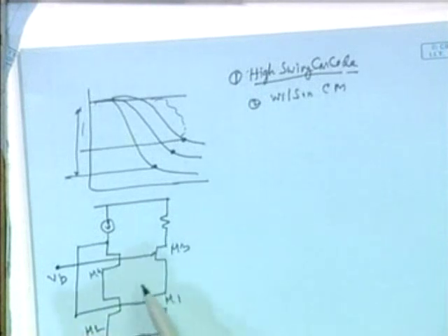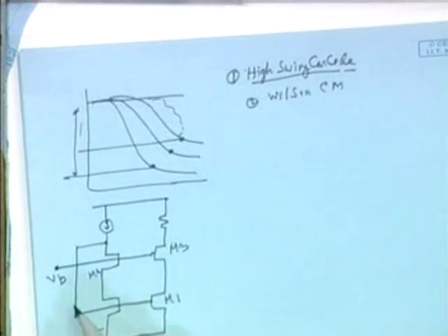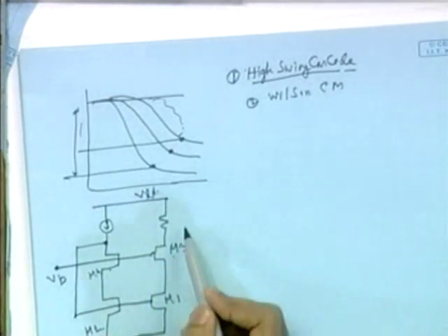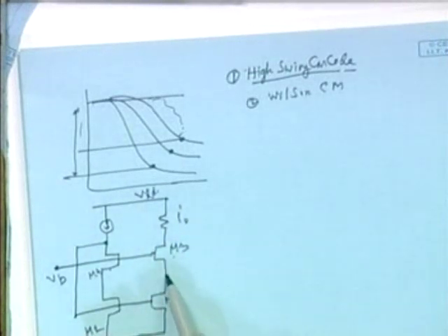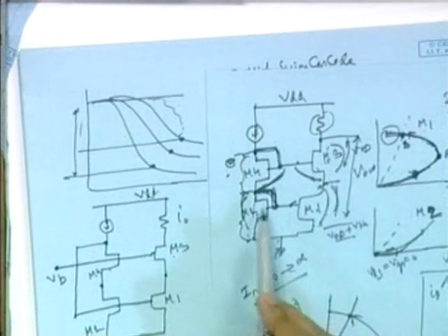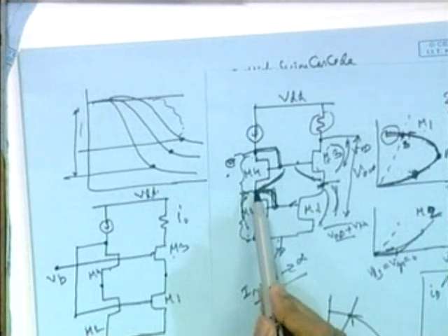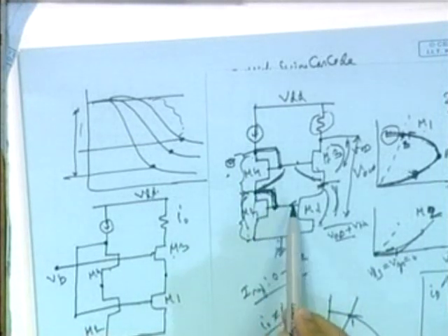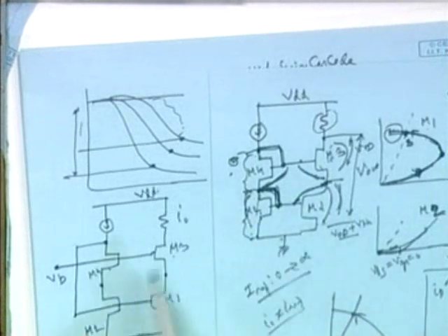Here, what we do is that the gate of this M1 and M2 is connected to this point, and for M4 and M3 we are using a separate bias voltage VB. So what we gain here is that though these 2 points are tied together, virtually tied together, this is not tied to the gate, because previously this voltage and this voltage were the same, and this was shorted to the gate. So basically these two are shorted. So here, as this is not shorted, no path is there.